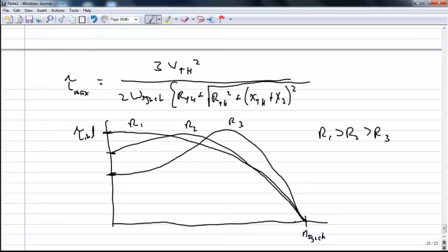You could imagine I could have this resistor that I switch in when I'm just starting the motor up and the speed is 0, and then once the load starts to move, I can switch that resistance out. The disadvantage of having that resistor there is that I'm consuming more power. I'm wasting power. But I can have it in there when I need it, and then switch it out as the speed moves closer to the synchronous speed.